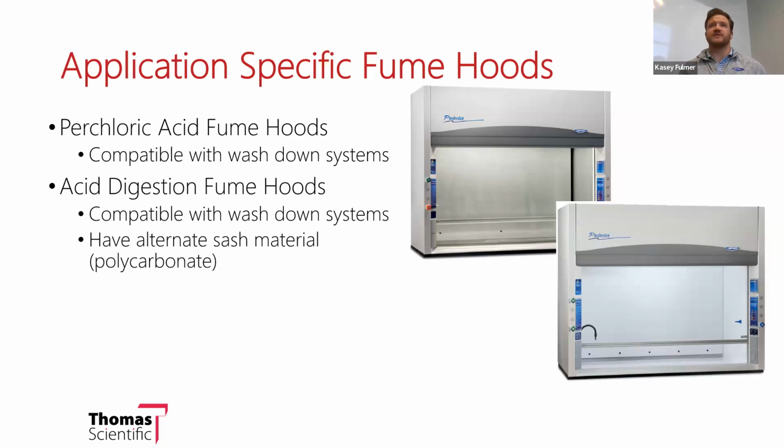They typically also have different materials of sash, such as polycarbonate or Lexan, which is compatible with hydrofluoric acid, which is oftentimes used in acid digestions, but it will etch glass. So perchloric acid hoods use glass. Acid digestion hoods have Lexan, because the perchloric acid will crack or craze the Lexan, but hydrofluoric acid will etch glass. So again, those acid digestion hoods will have a washdown and PVC and those Lexan sashes to make sure